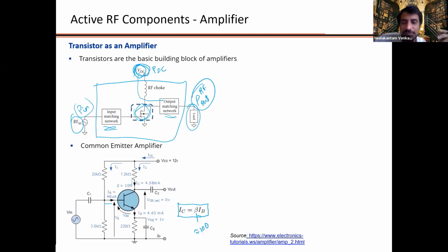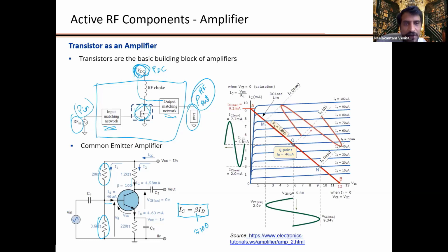But specifically, if you notice, there are these resistors that are called biasing resistors that will determine the Q point or the operating point of this transistor. What do we mean by that? If you look at, let's say, the collector emitter voltage, the VCE, versus the collector current that flows through the transistor, you would obtain a set of curves like this, which change for different base currents.